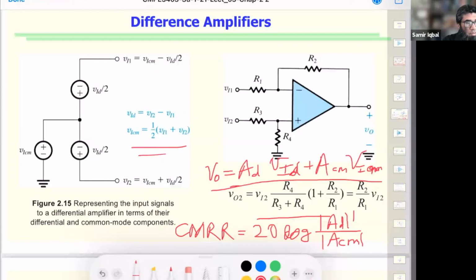For example, these two wires that run from the transducer to an instrument may get interference. Some places we need a differential amplifier. In all cases, with an op amp with infinite gain, we can control the gain, and what we achieve is that we reject the common mode signal.